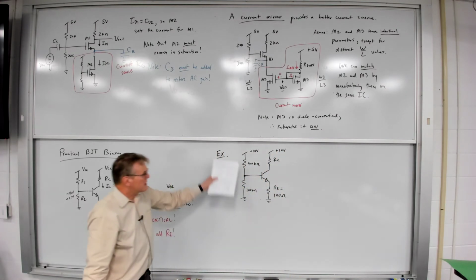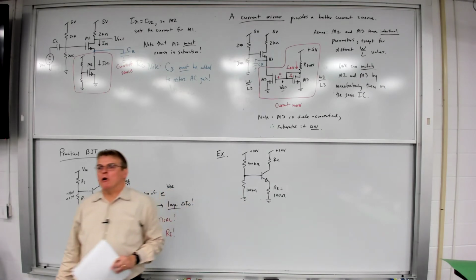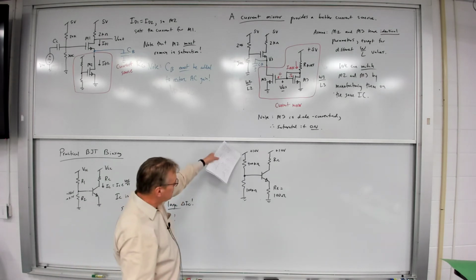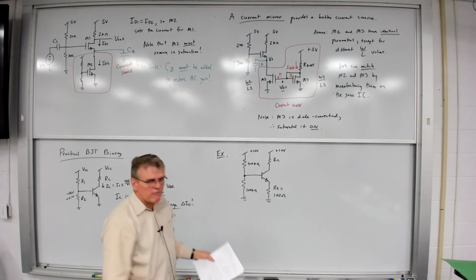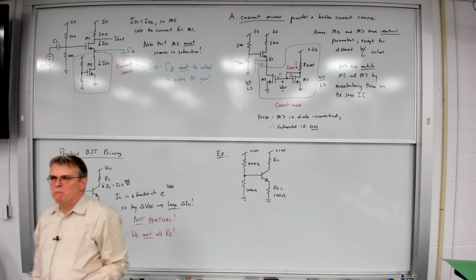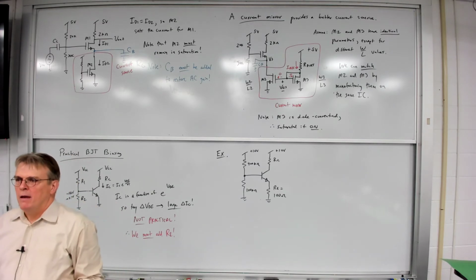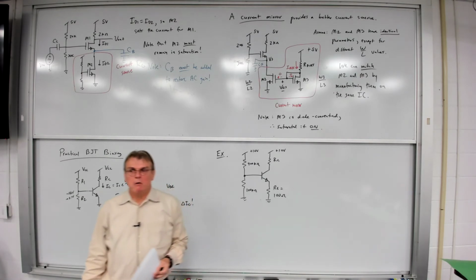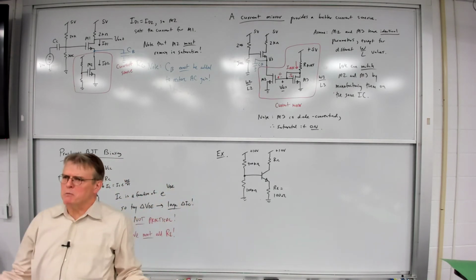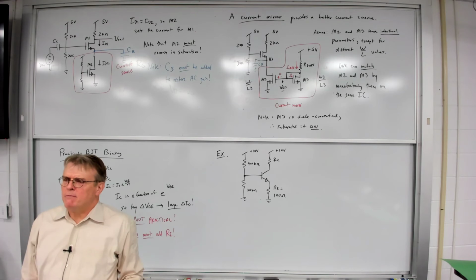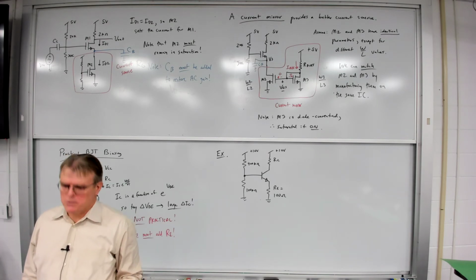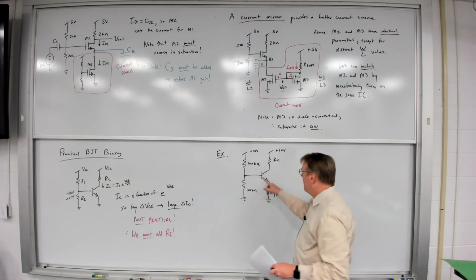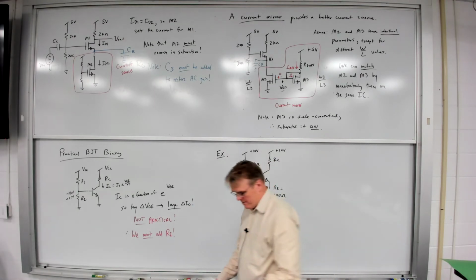So in this case, I put in a 100 ohm emitter degeneration resistor. And for these two resistors here in the base leg, I just kind of arbitrarily picked some big values, 400K and 100K. I'm not saying necessarily that any of these are optimal resistor choices. I'm just picking some values and doing some calculations to see how well this circuit works. Okay. Now, in a transistor,